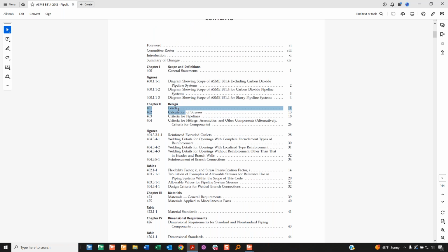My background is chemical engineering, so I'm not as familiar with mechanical engineering codes, but it relates because the codes are mostly about the materials, making sure they can handle whatever process you have. But what is going on in the middle of those materials, that's fluids moving through those pipes, right? And having these pressures, it will be from the fluid that you have those surge pressures. So you've got to make sure your pipes can handle it.